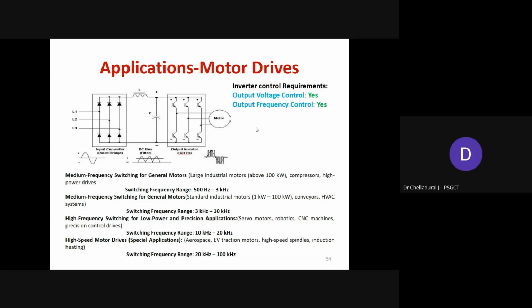The reason is, while increasing the switching frequency, we already know that each and every turn on and turn off process involves switching power loss across each and every switch. So before increasing the switching frequency, the load parameter, especially the load power magnitude, should be considered as one of the very important performance parameters.